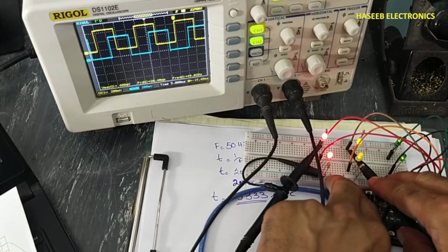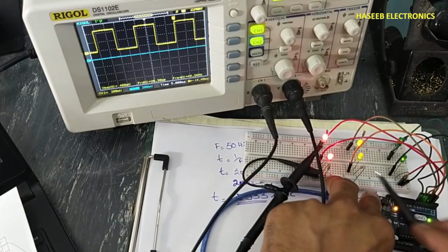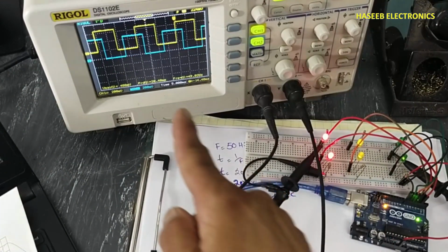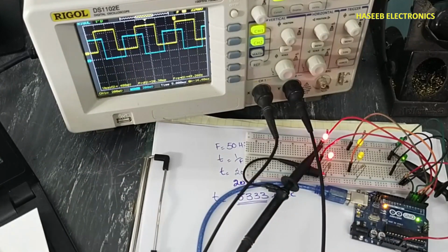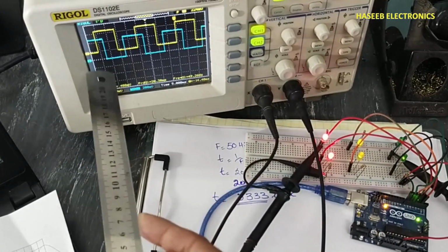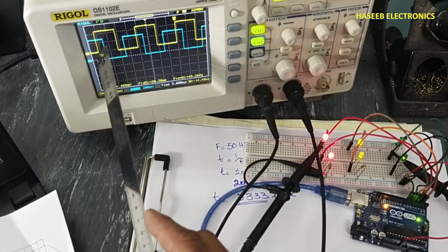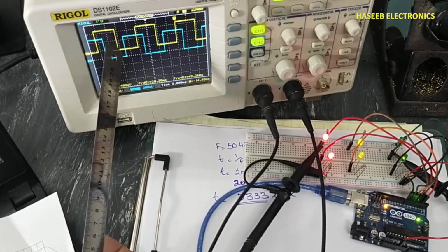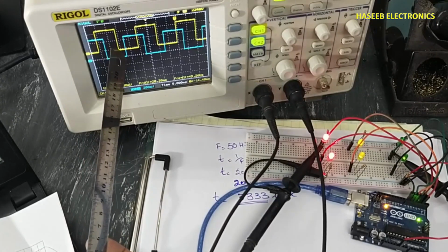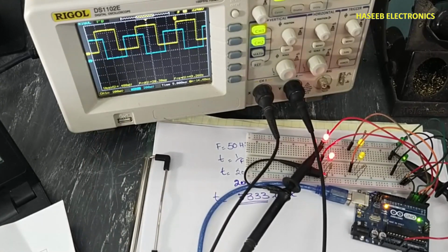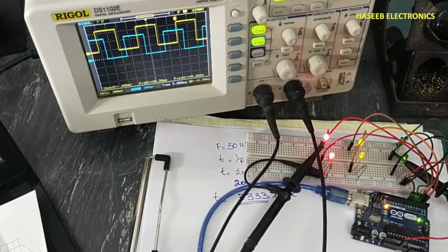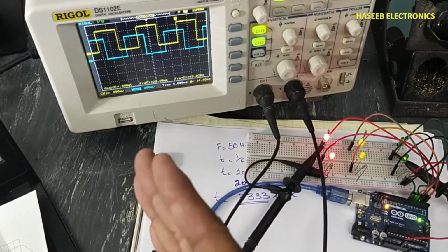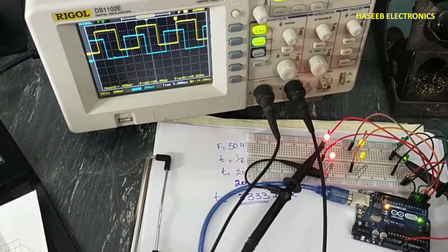Now check signal C. Yes, we can see when channel A has crossed 0 and is on the negative side, then signal C is starting. So we have exactly 120 degree phase difference in each phase.